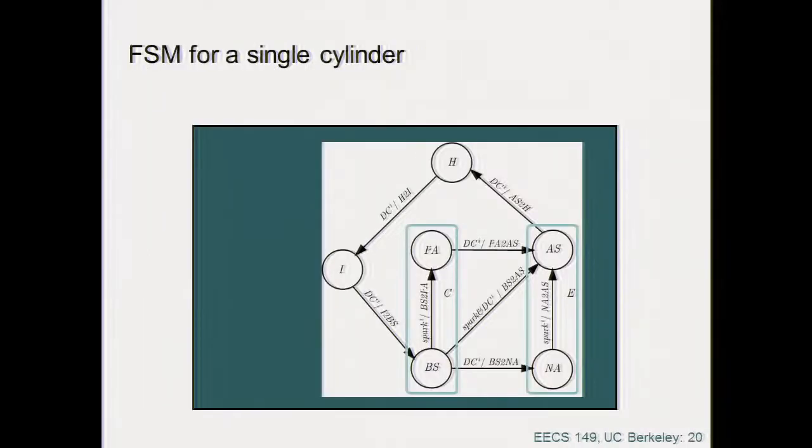is the command of what the torque will look like. Now, here it is. That's a finite state machine. No more 4 states, but if you look at it, there are 6 states. And the 6 states correspond to the fact if I anticipate the spark or I delay the spark. Now, you could do a continuum between delay and spark, but nobody does it. Too complicated. So there are only 2 states, either anticipate or delay. End of story. And that's the reason why 6 states are good enough.